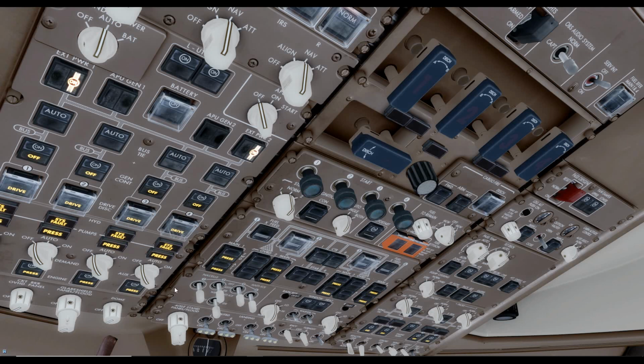Then moving down to the anti-icing panel, all of the selectors should be in auto. If you're operating an aircraft with the manual push button anti-ice selectors, then obviously the anti-icing should be off at this stage. But if you have the automatic anti-icing function, as this aircraft does, then all of the switches are left in auto. To the right of there, checking the wipers are off and the window heat selectors are both on and no fault lights illuminated.